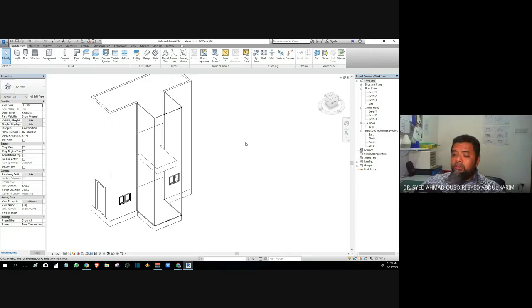Now, in creating this frame, it is customizable, meaning it depends on us. What is the size of the panel? The dimension and all those things. We can create it on our own. Okay. So to do that, before we put the frame, or it's known as the mullion, we have to determine the grid itself. Okay, we have to draw the grid first, and then we put in the frame or the mullion.